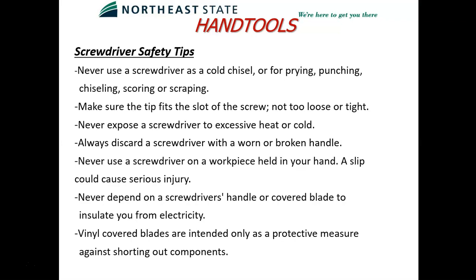So there are safety tips. We've already mentioned some of them, but one thing I'll point out is the third bullet down: never expose a screwdriver to excessive heat or cold. I'd say that for every tool, not just screwdrivers, because tools are made with hardened steel, and when you heat things up, they lose their temper.